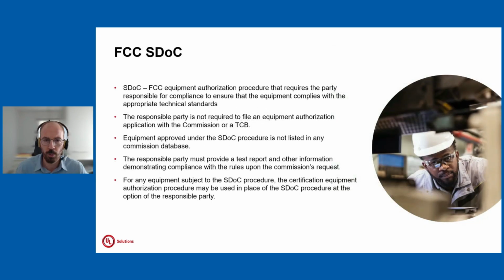Now, when it comes to the Supplier Declaration of Conformity, as mentioned, it is a self-declaration scheme. So the manufacturer needs to write down a declaration saying that the product is in conformity, but before doing that, needs to be able to demonstrate compliance. The compliance in this case is typically demonstrated against the so-called FCC Rule Part 15 Subpart B. This is in general the most common rule part. We are not talking about standards, but about rule parts, so it's FCC legislation, US legislation. This addresses the EMC requirements. If you want to consider an equivalent in Europe, this would be more related to the EMC directive.